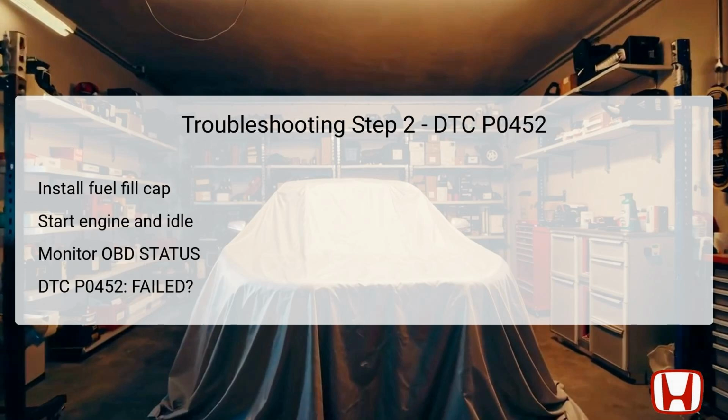In this step, after recording the initial readings, reinstall the fuel fill cap securely. Start the engine and allow it to idle so the vehicle can reach its normal operational state. While the engine idles, utilize the HDS to monitor the OBD, onboard diagnostic status, for any indication related to DTC P0452. If the HDS shows failed, this confirms that the issue is reproducible, allowing you to move forward to step 3. However, if the system indicates past or intermittent failure, it signifies the system is functioning correctly at that moment.